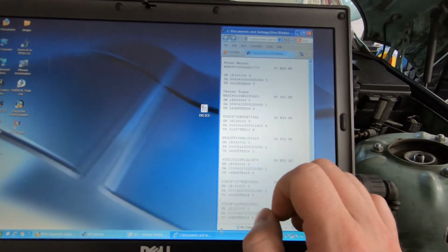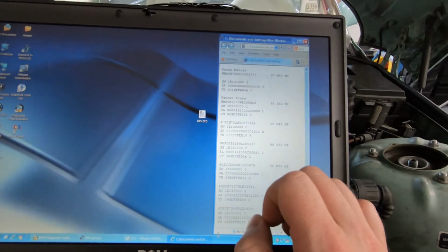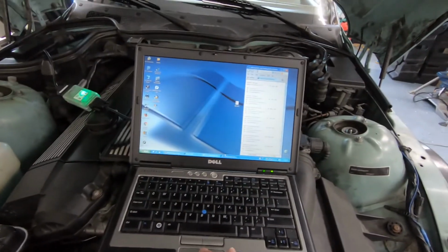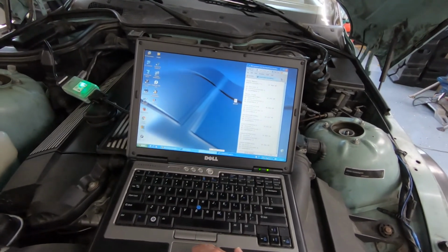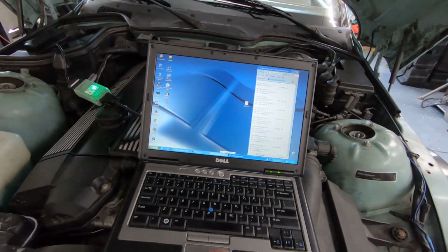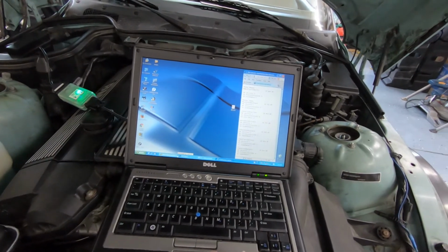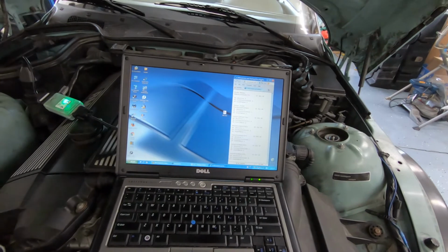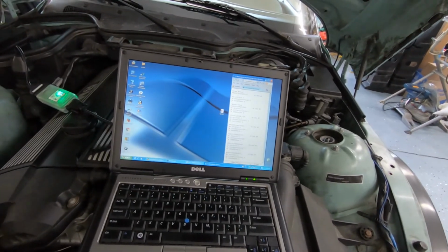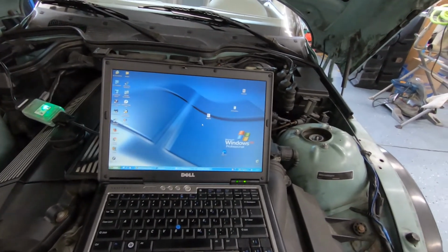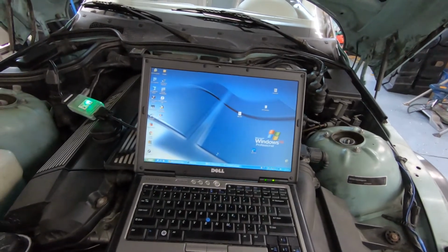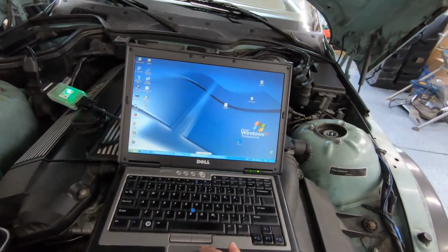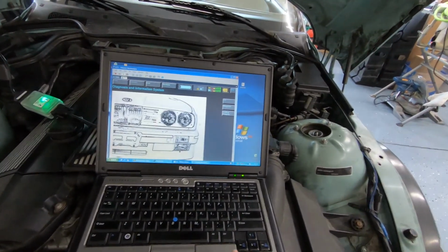and now I'm at a state where I do not have the automatic transmission control module in. All the codes are cleared, ASC is happy, engine is happy, and the only thing left is that one gear warning light, which, since the transmission control module is no longer connected, I don't really care about. I just wanted to make sure that all the other modules were happy. Alright, that's kind of putting the cart before the horse here though.